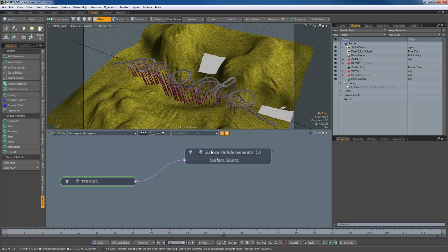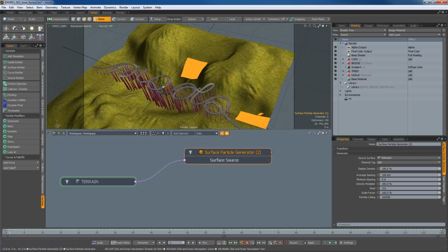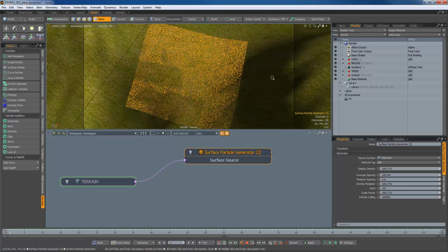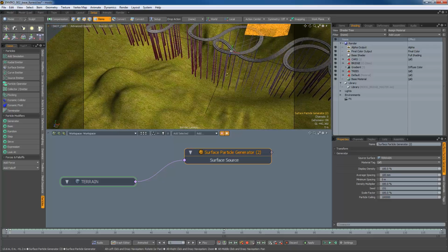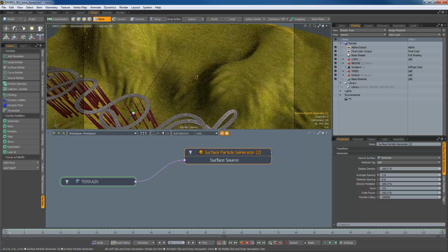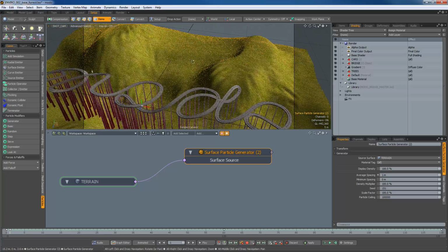What you'll notice is that the particles do clump in a confined space. They are all on top of each other, and the reason for that is that these are actually being spaced too close to each other. So now I know that a number that worked for this particular setup was around 1 meter. And as you can see, now they are distributed nicely across the whole area.